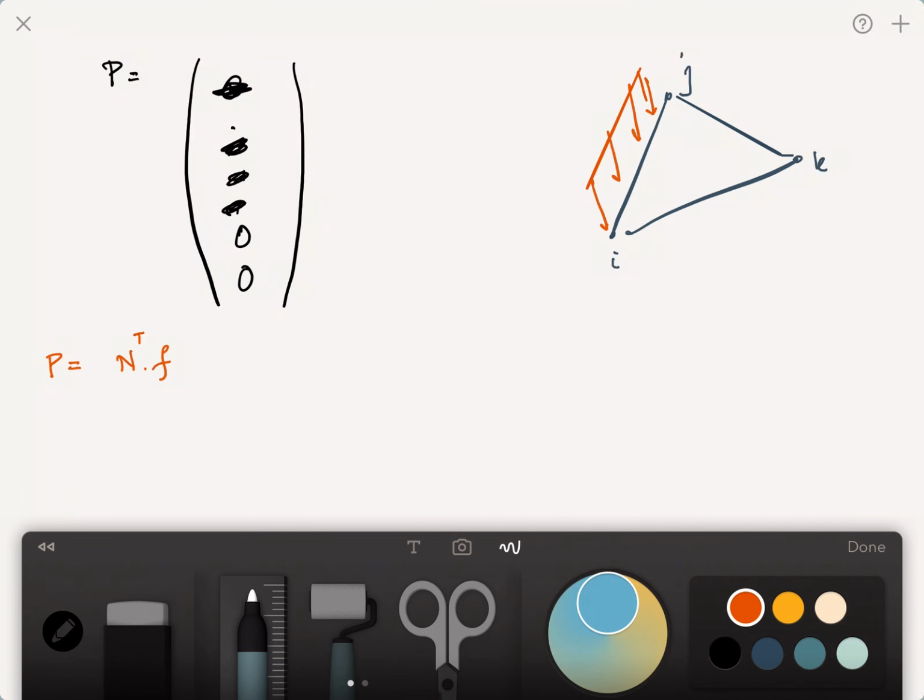Once you apply this shape function, you will see that if you have a distributed load, it will divide the load at this node and at this node, and you'll be able to find the values in a certain direction. So you have to find the components in x and y, and then put in px, px in both directions, and py, py. So that's about the force vector.